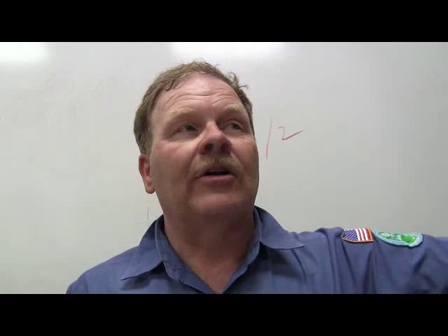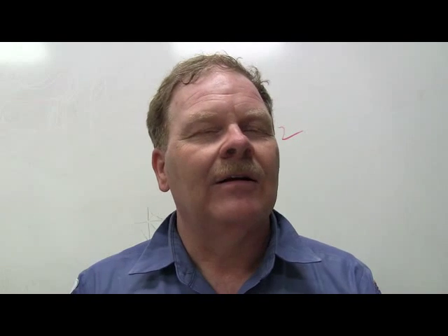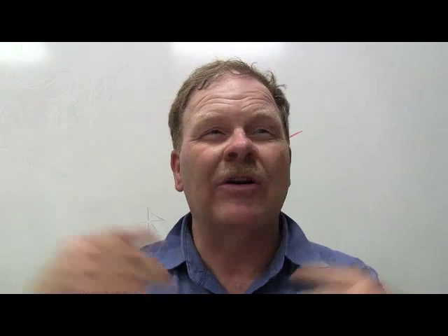I'm going to keep feeling that thing, and I may turn off my refrigerant, let it run a little bit, and when it's cold all the way to that compressor, I'm done. You got me? That's how you're going to tell. When it's cold all the way to the compressor, you're done putting refrigerant in it, if you're just doing it on a tractor or something like that.